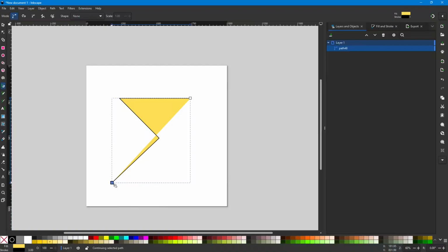And I will just demonstrate that because you can add on to a path after you locked it in just by clicking the last node and then going up and clicking the node that you started on or your next node. Let's say I wanted to bring it out here and then come over to here. So you see how Inkscape is now showing you, hey, this is the complete path. Now I'm going to back up just one by hitting Control Z, but that's the idea here. If you have a fill set, when you get done clicking the path, Inkscape shows you what it would be if you actually completed the path like you have it right now.